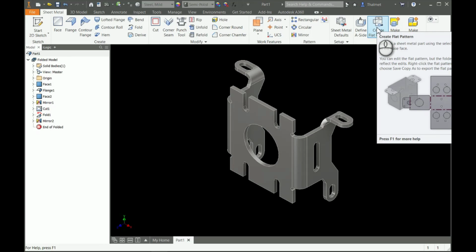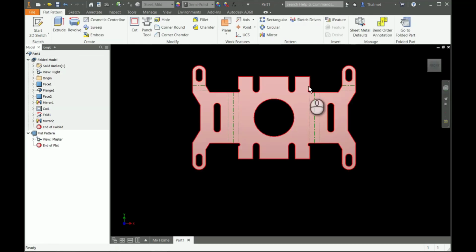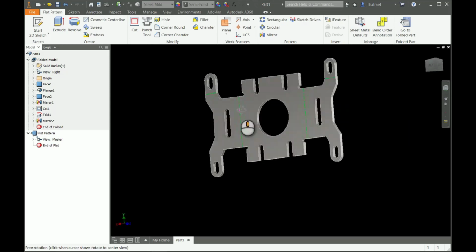So that's pretty amazing, to where I can get the pattern I need, put it on a piece of paper, trace it out, cut it out, hand it to a fabricator, and he can get on his way. It is astounding what we can do with this. So I'm going to go ahead and click it. And there we see our actuator bracket in the flat.